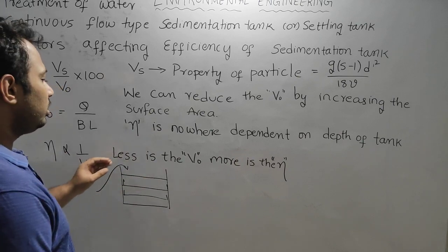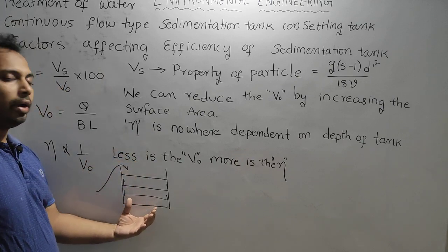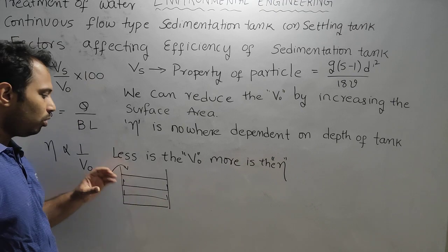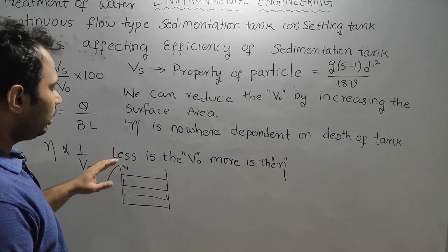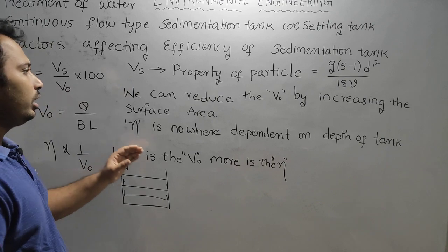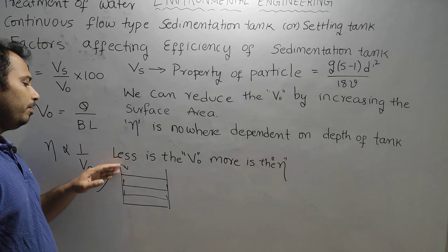That means the surface area of the sedimentation tank has increased without altering the volume of the tank, simply by reducing the depth.